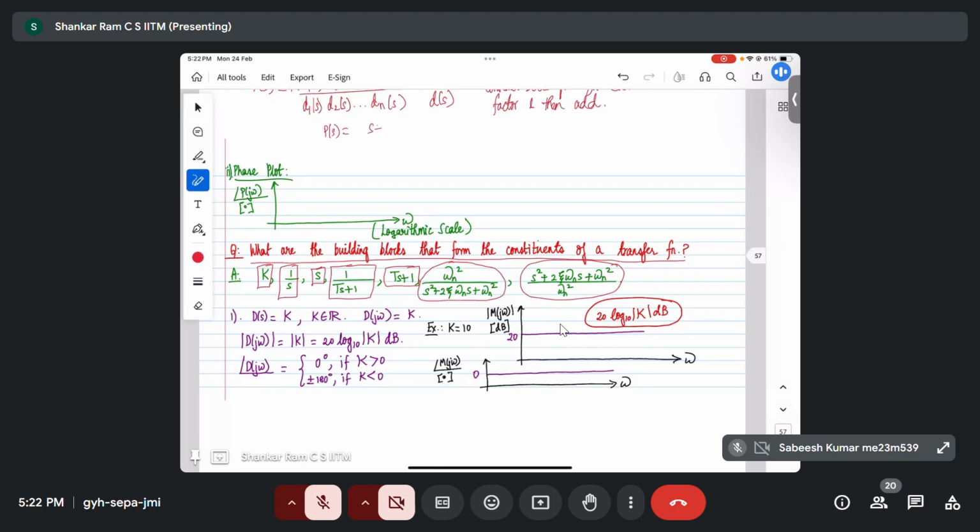So let's understand. Let's say I have some transfer function (s plus 2) times (s plus 4) times (s plus 1). I'm taking it arbitrarily. So this I can write as 2 times (0.5 s plus 1). Then the denominator, the first term I can write as this. Second term I can keep as s plus 1.